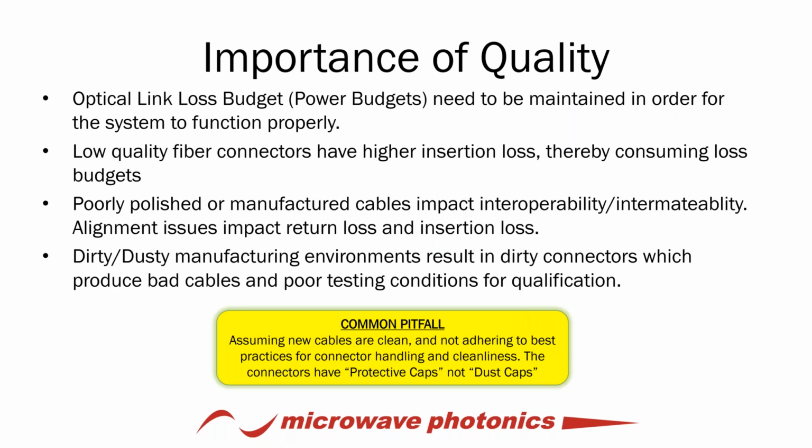Next common pitfall: assuming new cables are clean and not adhering to best practices for connector handling and cleanliness. A lot of people refer to the caps on the end of fiber optic connectors as dust caps, and that couldn't be further from the truth. They're protective caps. Don't ever assume that just because you've taken a new connector out of the bag from a manufacturer, even with a certified test report, that it's clean. A lot of these protective caps are made out of plastic. They tend to attract dust, and they absolutely need to be cleaned before being connected to the equipment.